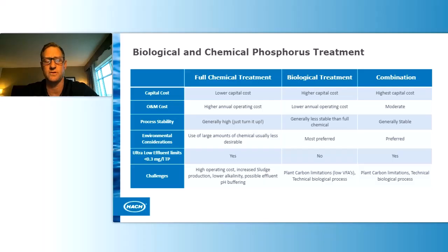We'll remove phosphorus biologically, and we try to do it primarily biologically. And then maybe we'll have a trim system using various metal salts to trim the system. And this can be exceptionally helpful when our facilities have very low phosphorus limits. That can be helpful.